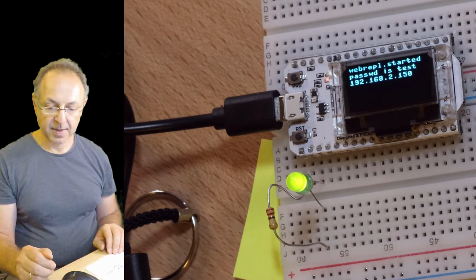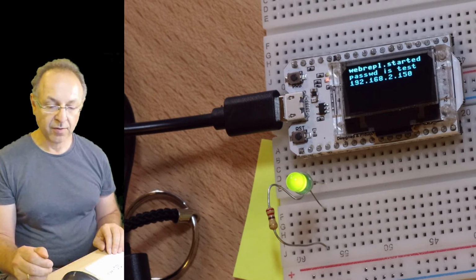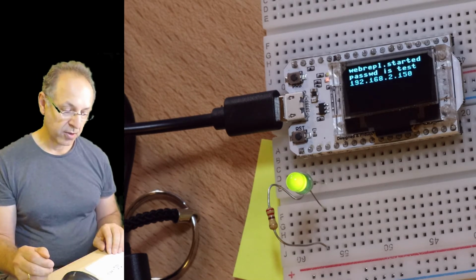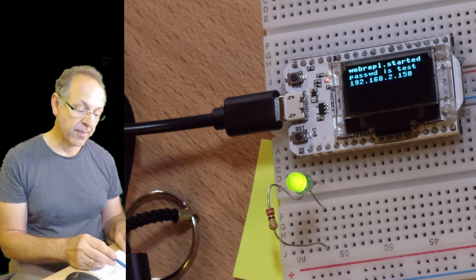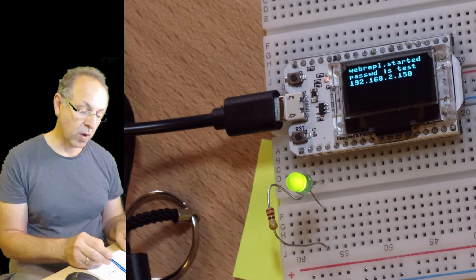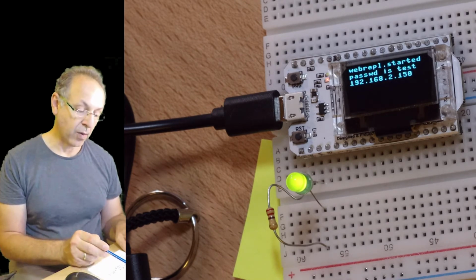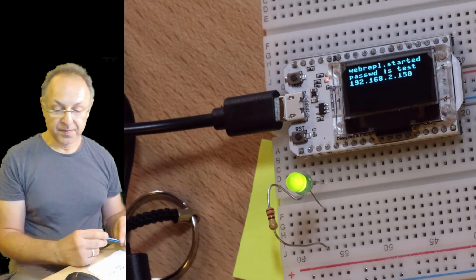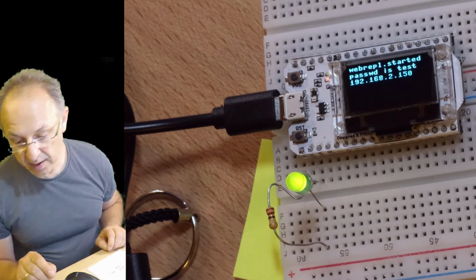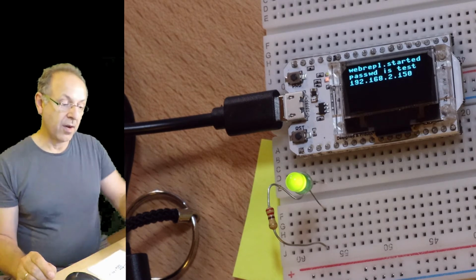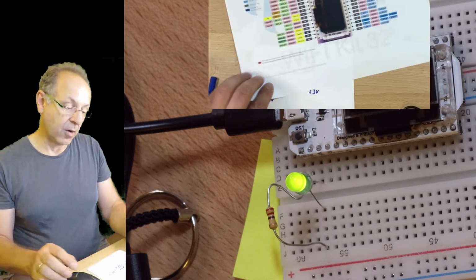The next step is to look for a pin that we can switch on and off and build up the same circuit. So we don't connect to a constant 3.3 volt. We connect to something where we can either say this is 0 volt or this is 3.3 volt. Now, if we look at the LED, now it's connected to 3.3 volt.